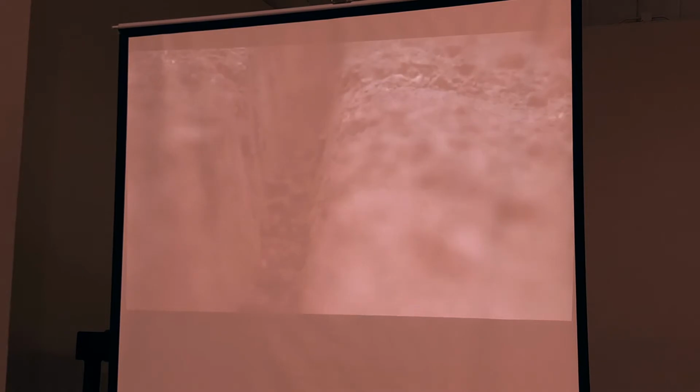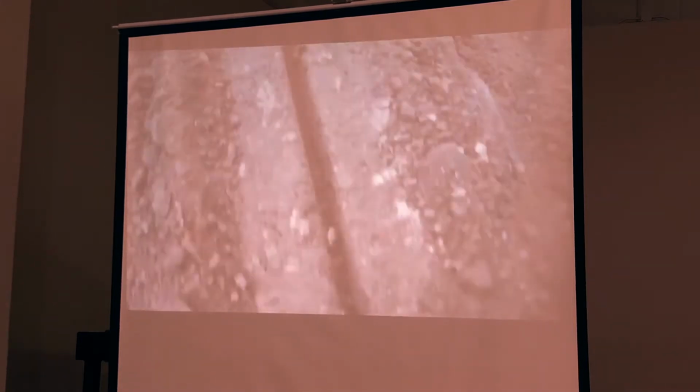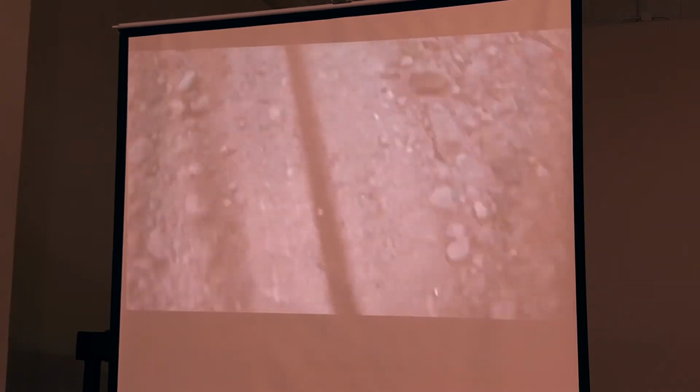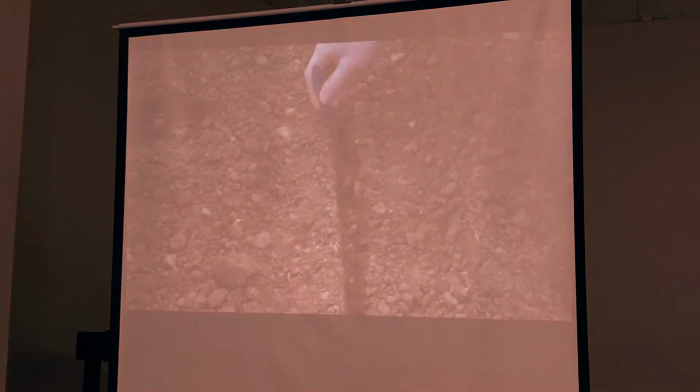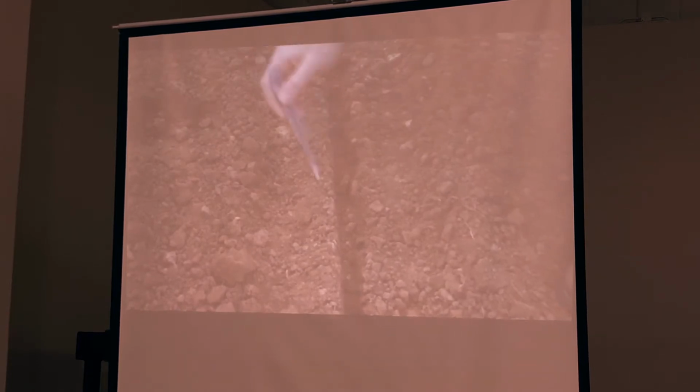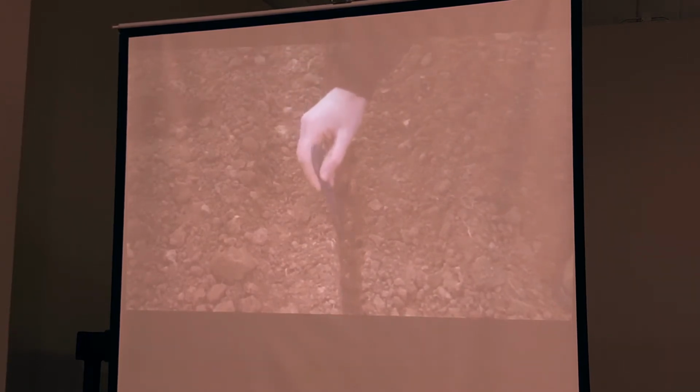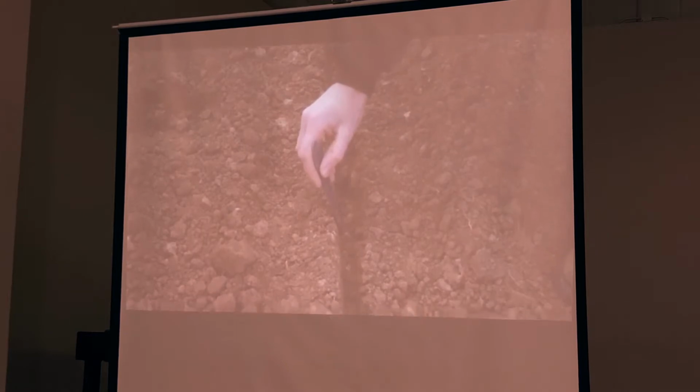There are many signs when downforce margin is not properly set. Too little downforce margin will prevent the opener from planting at a consistent depth because the gauge wheel may intermittently come off the ground. Too little margin may also cause the seed furrow to collapse in front of the seed drop, resulting from too little pressure on the gauge wheels.